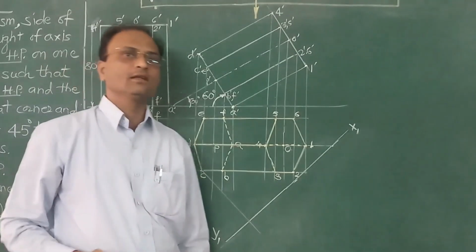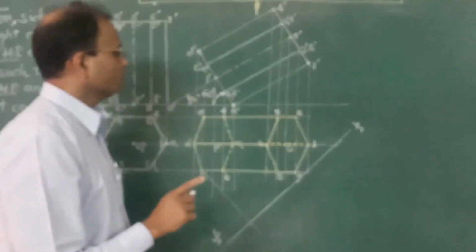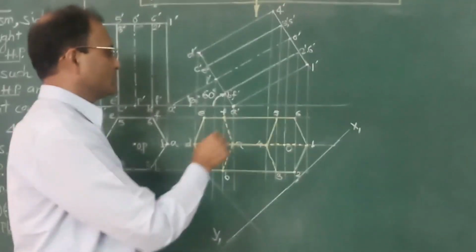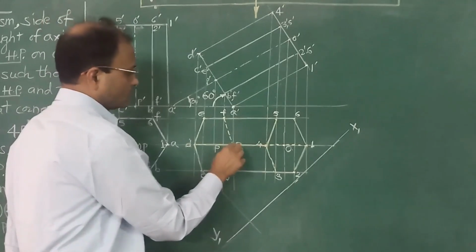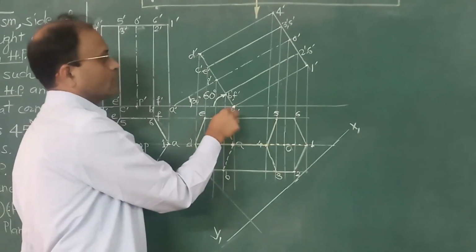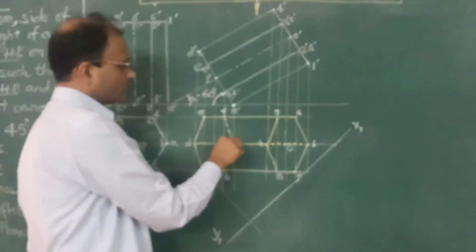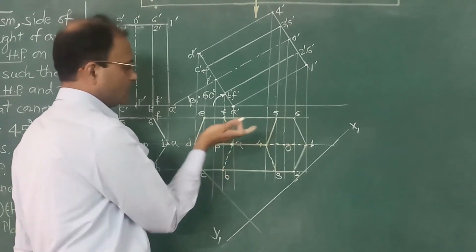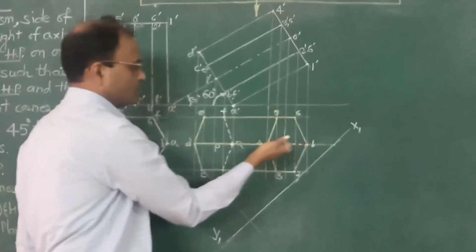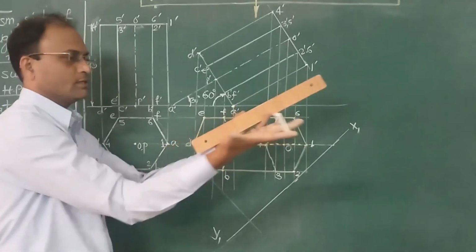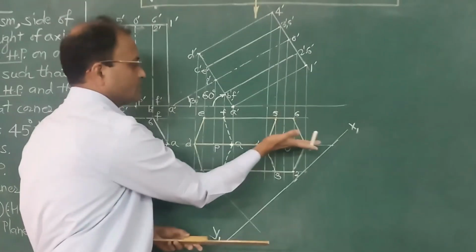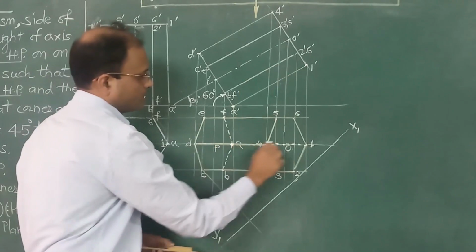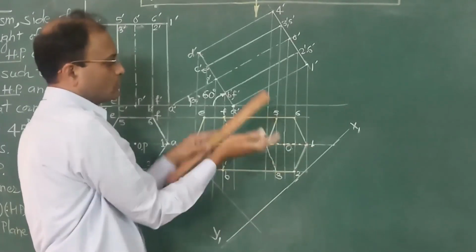Now let us apply second inclination. Here second inclination is of the plane. Now here the plane is seen as a line. We can see the plane containing that corner. So which corner is on HP? Corner A is on HP. So plane containing that corner and axis. This is the axis. So plane containing corner and axis is nothing but this line. Actually it is a plane surface, but in top view it will be seen as a line. So this plane makes 40 degree to VP. Right now that plane is parallel to VP. So we have to now tilt the solid.